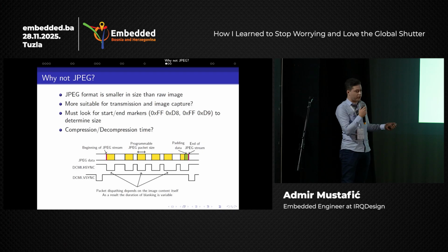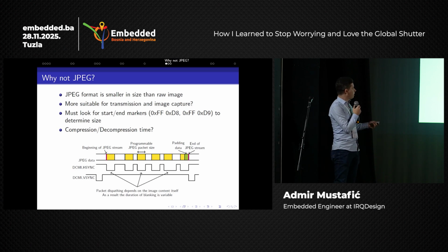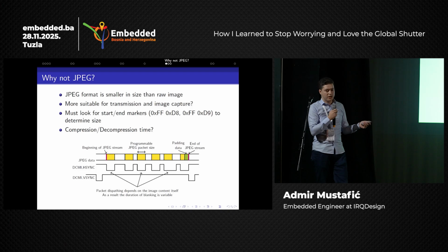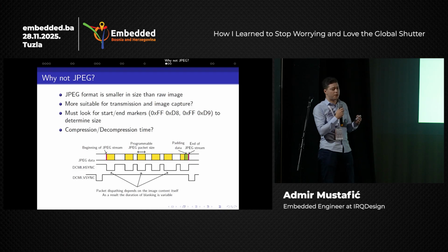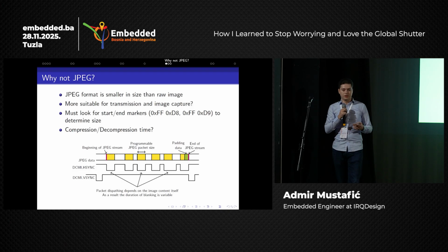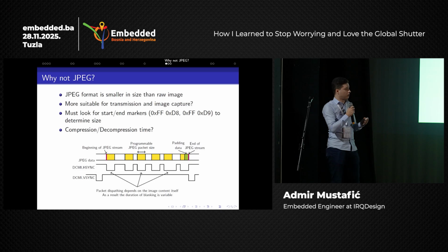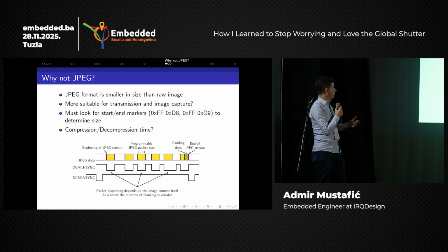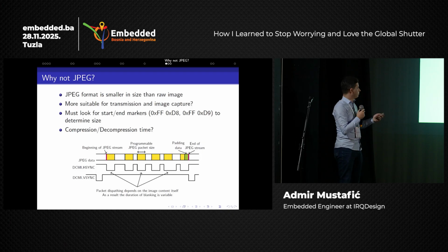But the JPEG packet sizes are in themselves programmable, which leads to variable blanking periods between each line and between each row. And with the variable packet size, we usually have some padded data if it's not aligned to 4 bytes, or if the frame capture has prematurely ended, we do not have the full programmed JPEG packet size. The DCMI peripheral will pad this packet with zeros.